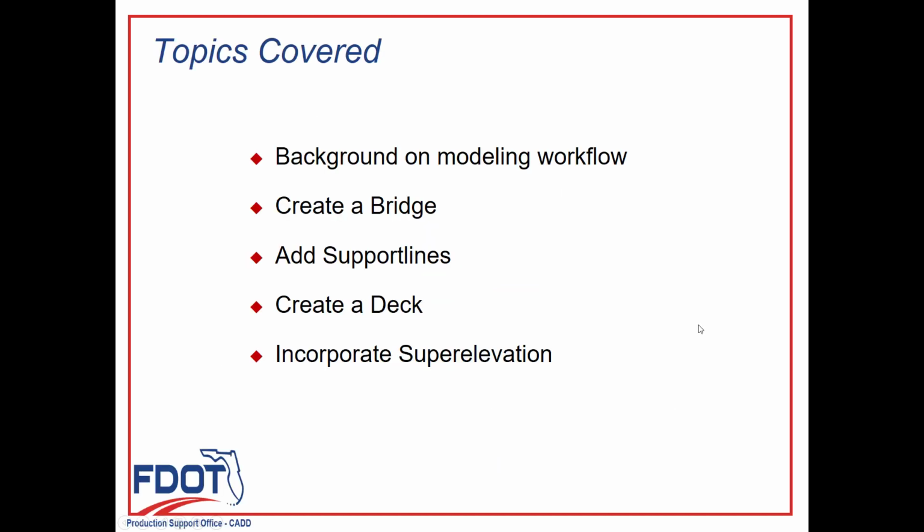So specific topics that we're going to cover in this video, we're going to look a little bit at the background on the modeling workflow, as this is the first video getting into the bulk of bridge modeling in Chapter 5. Then we are going to get into the software and actually create our bridge, add support lines, and then be able to create a bridge deck from that. We will also look at how we can incorporate any super elevation that might exist on a bridge. Let's get going.